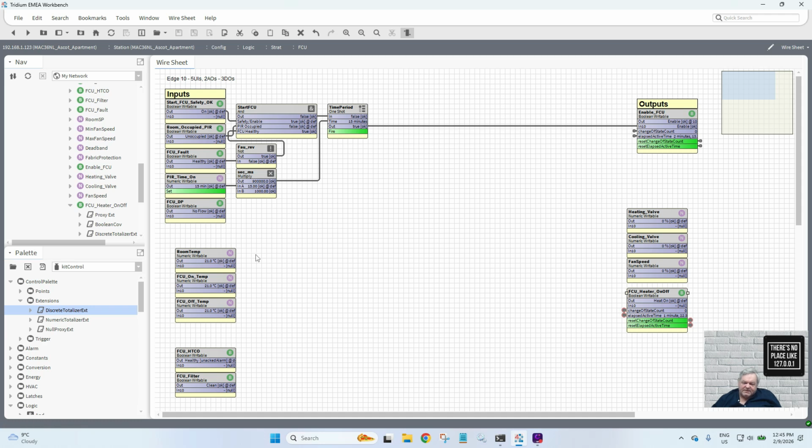Do we select heating or do we select cooling, depending on the set point, and then use the PI loop for that particular one? Let's have a play. The ideal would be probably just to use a PI loop for the heating or cooling. But let's have a play here.